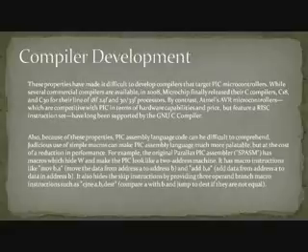Also, because of these properties, PIC assembly language code can be difficult to comprehend. Judicious use of simple macros can make PIC assembly language much more palatable, but at the cost of a reduction in performance. For example, the original Parallax PIC assembler has macros which hide W and make the PIC look like a two-address machine.